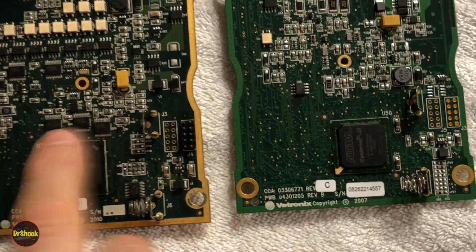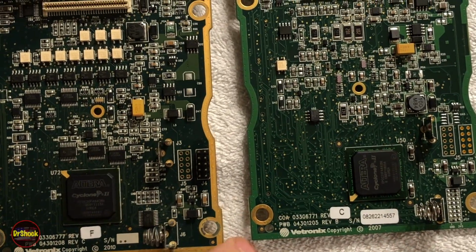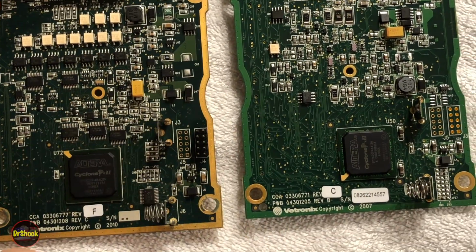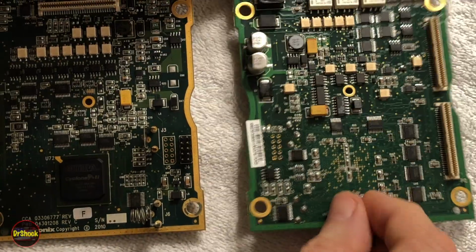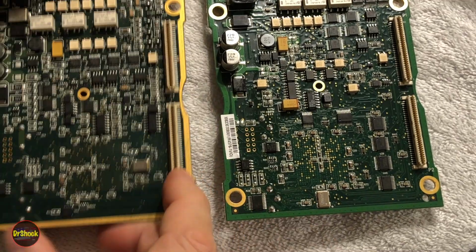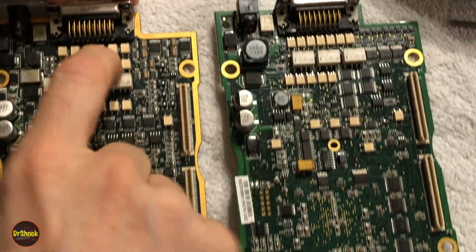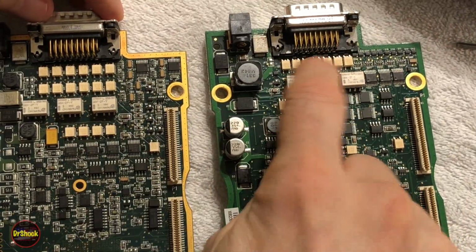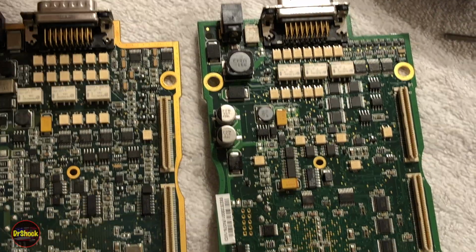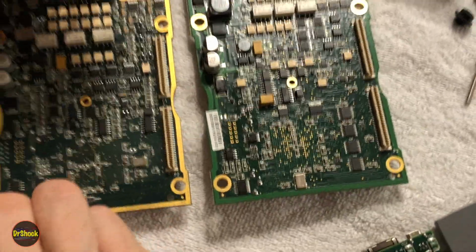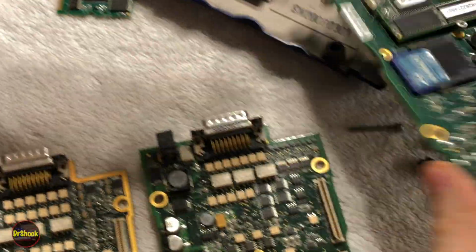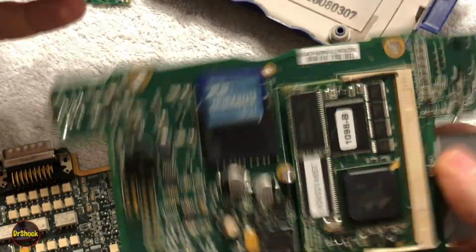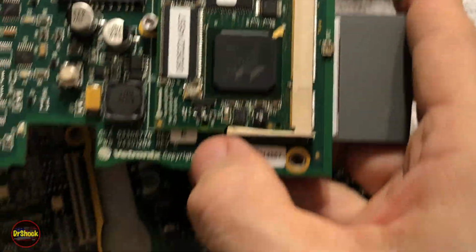We can see that the board's population has changed. Obviously, this F board is much more robust in its construction. A lot more buffering, probably a lot more ESD. On the top side, also we can see 2 rows here of devices, only 1 row here. So these are 2 different boards, and so mixing and matching them like that could be problematic. What we want to make sure, though, to do that is we want to take a look at these top boards, and we want to see what level these are. And so we can see that this is a G level, and this is an E level.